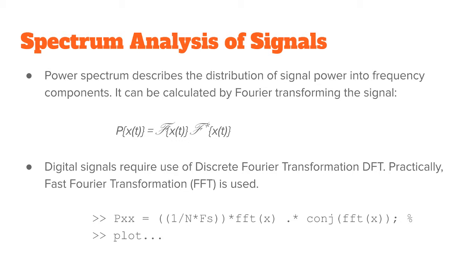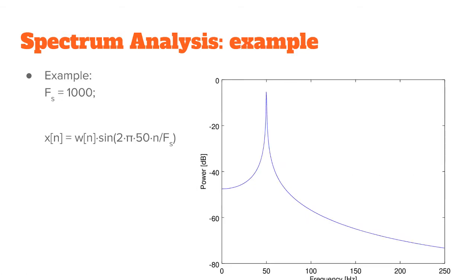However, there is a caveat. The fast Fourier transformation works only if the number of samples is 2 to the power of some constant integer. So 2048 is okay, 4096 is okay, 8192 is okay, but 8193 is not okay. Okay. Then there are some other artifacts.